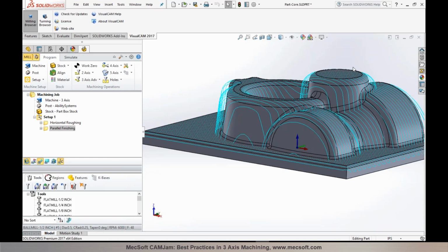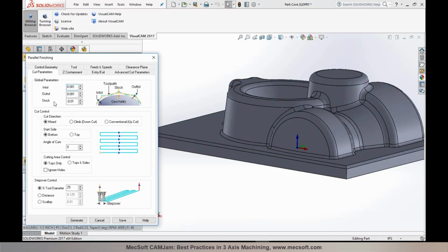So this could be an application where you need to apply some sort of a coating or a resin on top of the finished part, so that brings it back to the actual geometry of the part. Or if you have parts that need to fit into tight tolerances, you may want to slightly shrink it rather than having to go back and modify your actual CAD geometry to have it resized or shrunk. You can actually do this in the operation itself, where you can specify a stock.